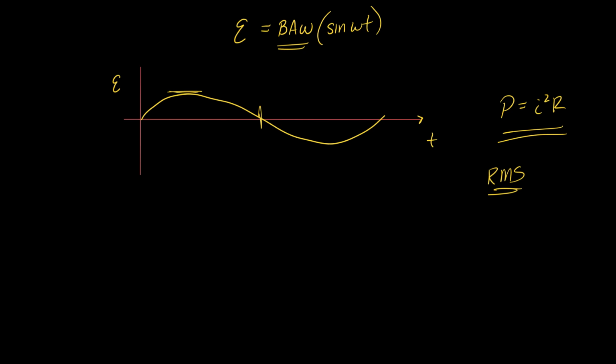One way to estimate it is called an RMS, root mean square. You do it in opposite order. You square the function first. That makes all of it positive. You then compute the average over the cycle, and then you take the square root. It's a way of calculating an average for something that has an average of zero. And it's used all the time in anything that's sinusoidal because it has an average of zero all the time. So one way to deal with that is called the RMS.